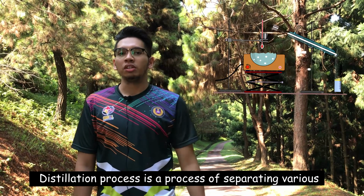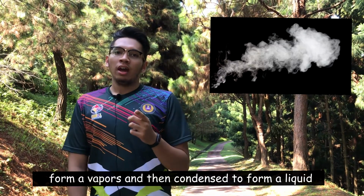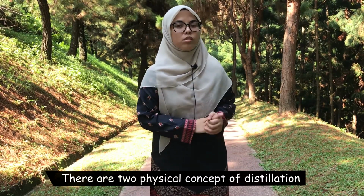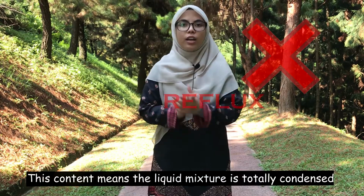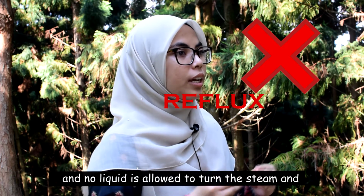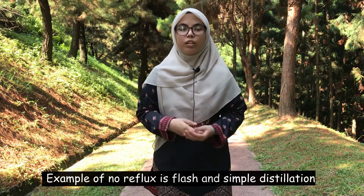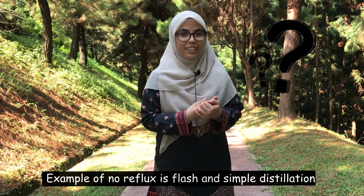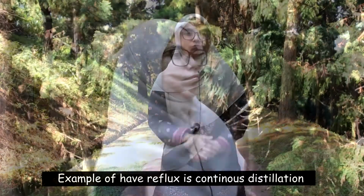Distillation is a process of separating various components of a liquid solution by heating the liquid to form vapors and then condensing them to form a liquid. There are two physical concepts of distillation. First is no reflux and half reflux. No reflux means the liquid mixture is totally condensed and no liquid is allowed to return to the still, and it has low purities in the product. The examples of no reflux are flash and simple distillation. The example of half reflux is continuous distillation.